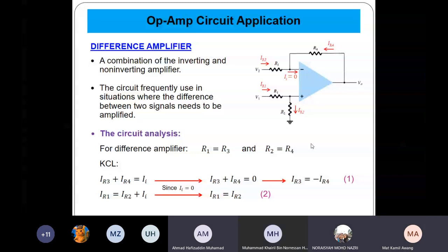This is the application. You have basically the inverting, non-inverting, then after that you have summing. Then now you have a difference amplifier. Basically, with the inverting you inverse the sign. Non-inverting basically just amplifies. The summing is you add. Difference is you subtract. Alright.